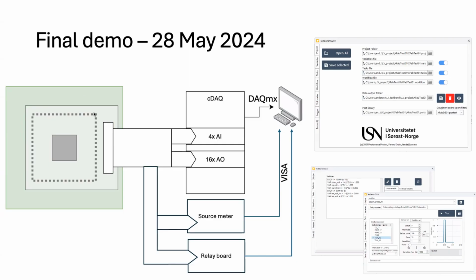So in general, as concerns the physical capabilities, here comes the test chip itself. You see my cursor, by the way? You do, okay. So the test system has 4 analog input channels through which it can read analog data from the test chip, then 16 analog output channels, which can actuate different inputs of the test chip.